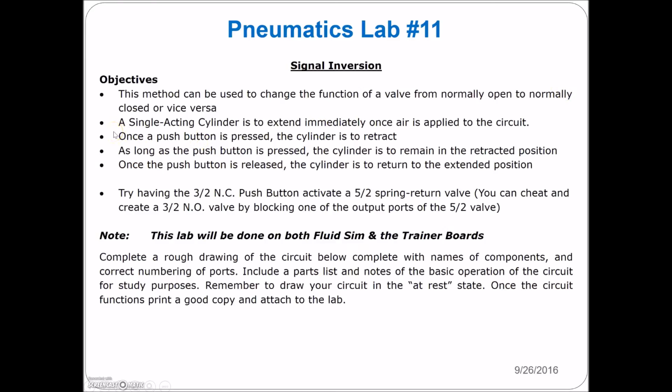So a single acting cylinder is going to extend immediately once the air is applied to the circuit. Once the push button is pressed, the cylinder is going to retract. As long as the push button is pressed, the cylinder is to remain in the retracted position. Once the push button is released, the cylinder is to return to the extended position.